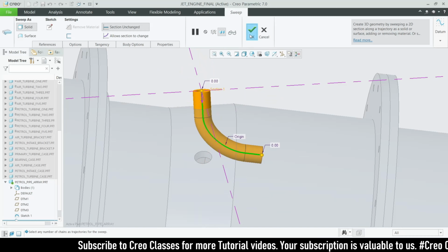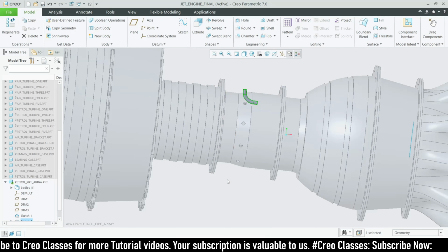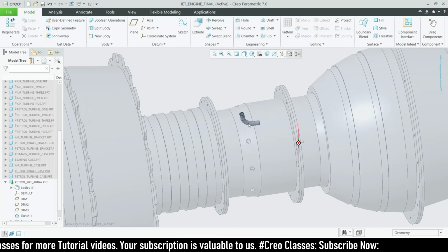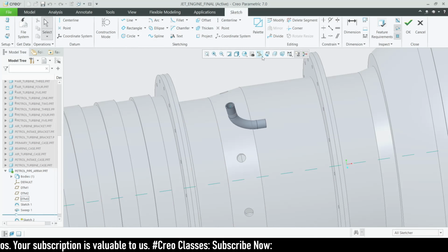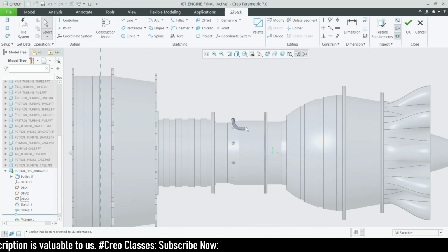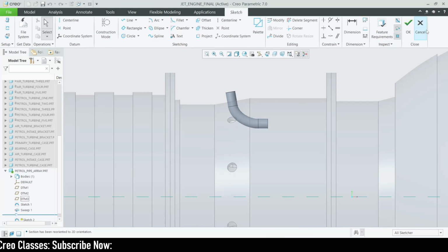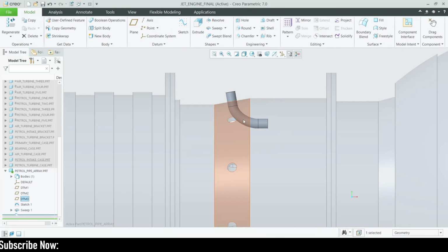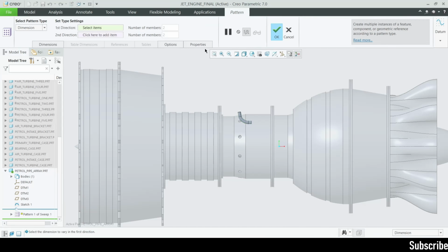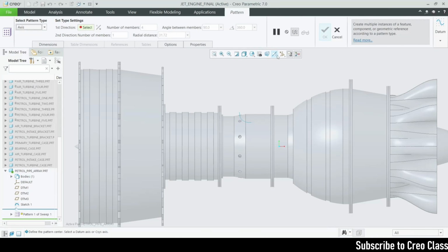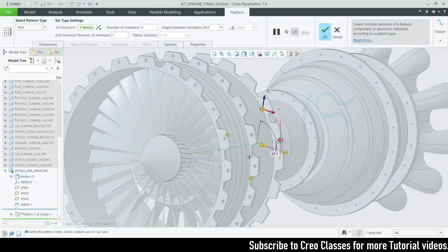It looks really good. I think this got placed perfectly. Or else if you need to check on this, you can go for the sketch and the sketch view, and here you can go for the sectional view. So you can see it is placed perfectly. Let's close this, select this sweep and go for the pattern, and for the axis pattern, let's turn on all these except axis display. Let's select the center plane.